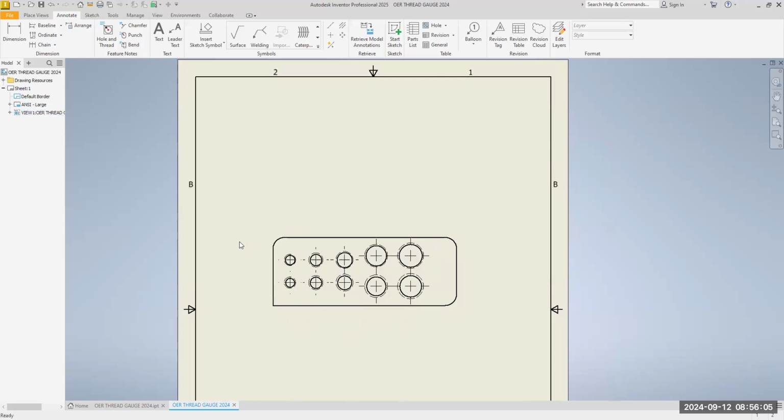All right. Now, watch very carefully, please. Over here, where it says Parts List and Hole, this is a hole table. Click on Hole Table, and then come down here to your view. Click on Hole, come down to your view, click. You'll see this strange little dot, part of it's black, part of it's white. What we're going to do is move it down, and we want to snap to that sharp corner. That's the reason I left it. Click on that sharp corner.